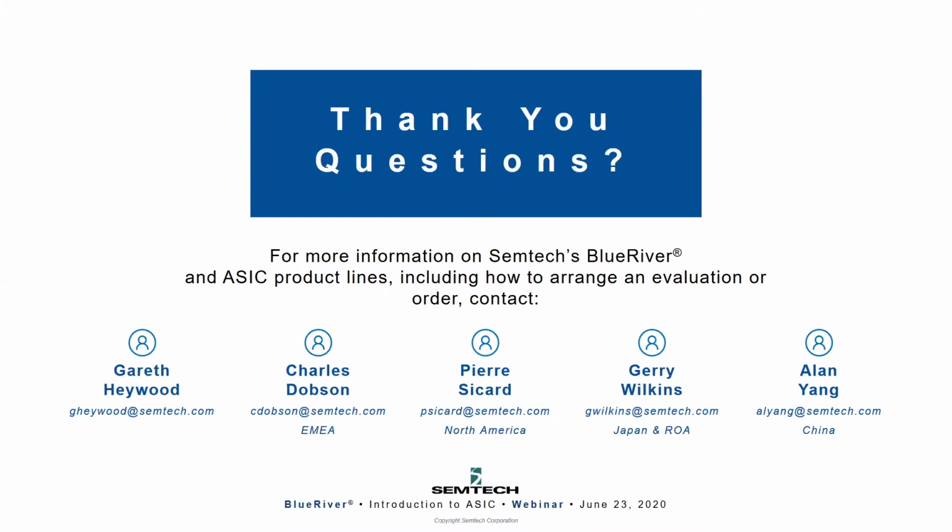Okay, and we got a follow-up question on HDCP. What are our HDCP device limits? Are we limited to 32? Really, that's a system level design. I can't think of any specific limit unless there is some limit to the HDMI transceiver that's used itself. Typically in a system, customers are not going to that sort of number of levels of handshaking.